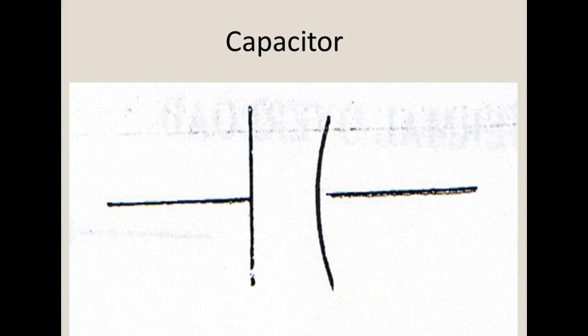Okay? That's a non-split phase motor so far. Because a split phase or a single phase motor has 2 windings. Now this motor here, y'all, works great. It just can't get it started. Won't start. So they've come up with different methods to start. This is one of the methods.